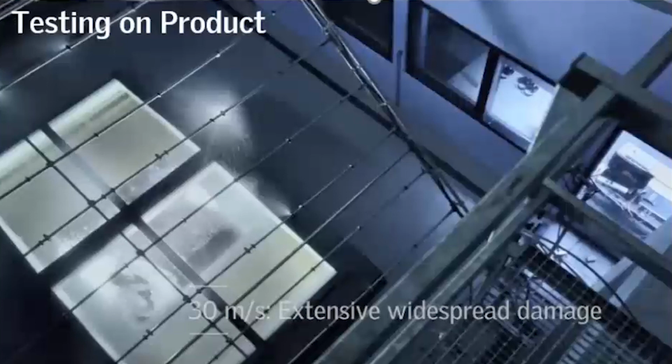What you're seeing here is a spray deck. So this is over top of a test skylight. This is in a wind chamber, so there is a large fan blowing air at 30 meters per second. So it's producing a pretty high wind while spraying water on it to simulate rain. And what you can't see in the image very well is there's actually a technician below the skylight with a flashlight who's inspecting for water ingress, so a leak through the skylight.